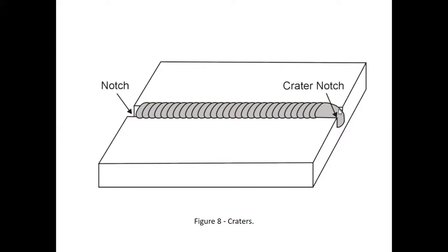We don't want to have those square walls. We want to incorporate all this into the weld. We want the weld to come right to the end of the plate. Also, on the same thing, we want to start the weld at the end of the plate. We don't want to come in a 1/4 inch or anything like that. There's going to be a definite hard transition between this 90-degree square wall and this weld, and that's going to be a point of failure.